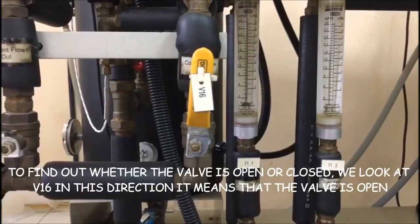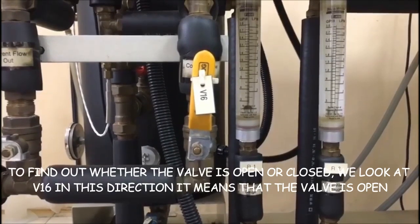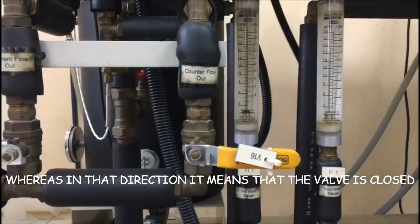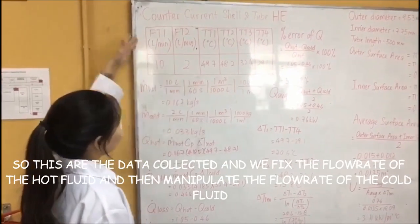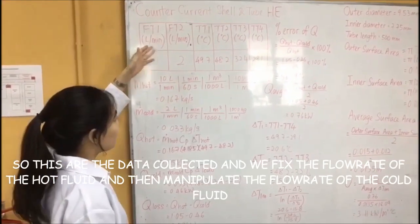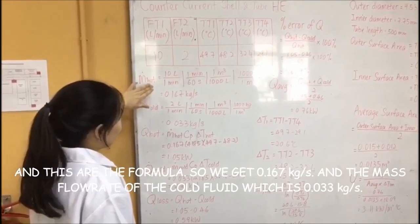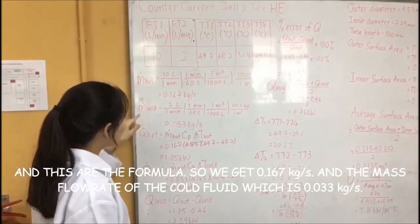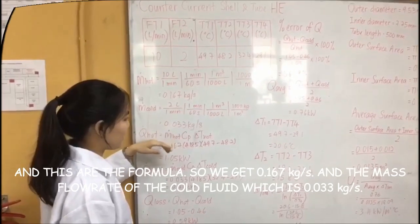To find out whether a valve is open or closed, we look at valve 16. In this direction, it means that the valve is open, whereas in that direction, it means that the valve is closed. So these are the data collected, and then we fix the flow rate of the hot fluid and manipulate the flow rate of the cold fluid. Now we have to find the mass flow rate of the hot fluid, and this is the formula. So we get 0.167 kg per second, and this is the mass flow rate of the cold fluid, which is 0.033 kg per second.